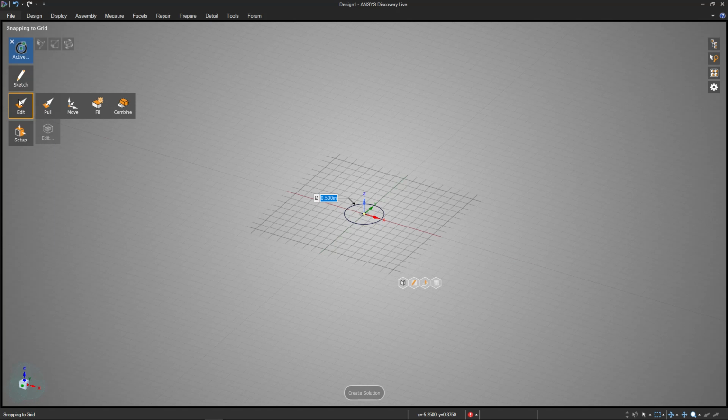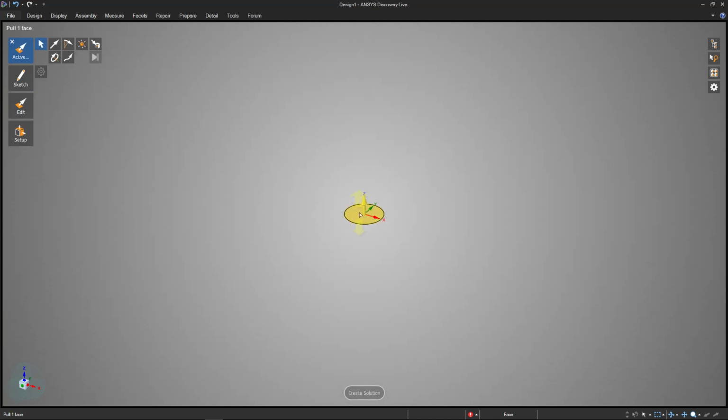Then I'm going to leave the sketch mode and go into 3D view by using the pull tool to take this circle and pull it up a certain amount. The length of our cylinder could be no less than 5 and no more than 7 inches in length, so I'll select 6 for our initial starting point here.